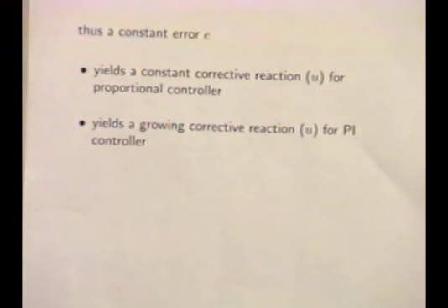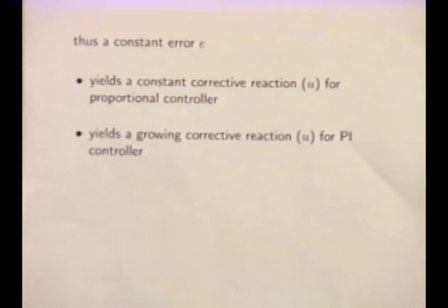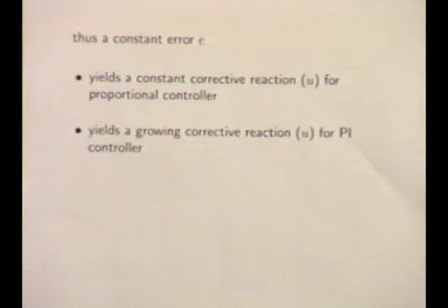Then I give you a correction, which the proportional controller will also give you. But if the system doesn't respond to that correction, it gets really mean. Instead of adding a small correction, it'll make that correction increase until it sees the system doing something. So it keeps penalizing you more and more the longer you take to get to the desired point.